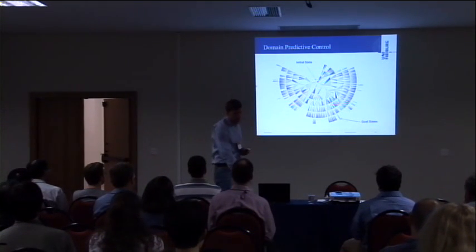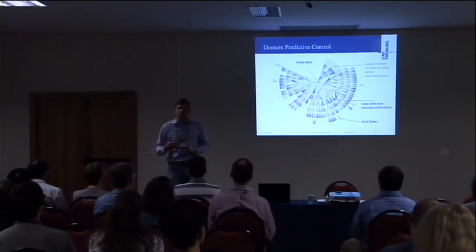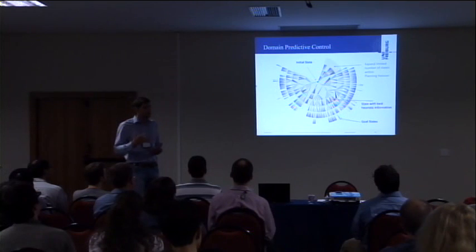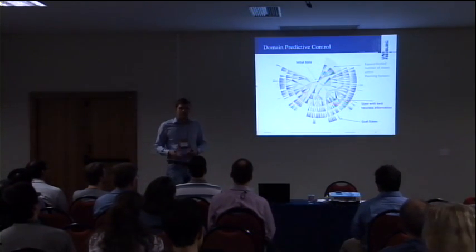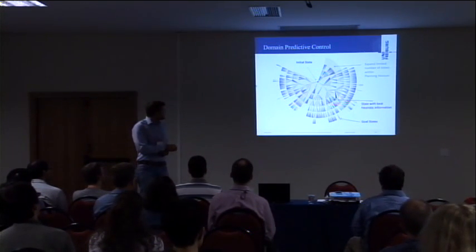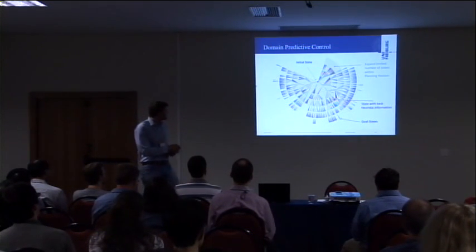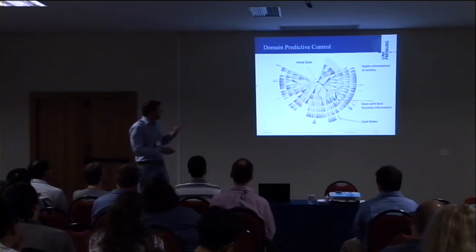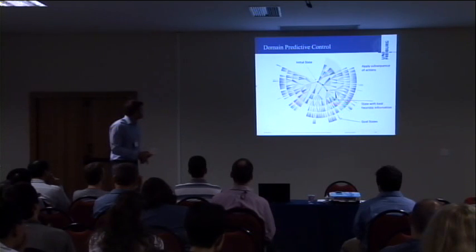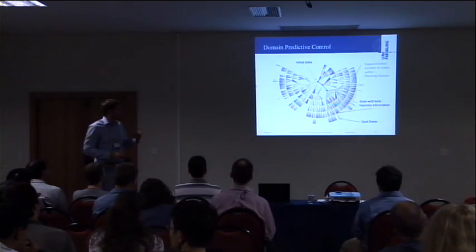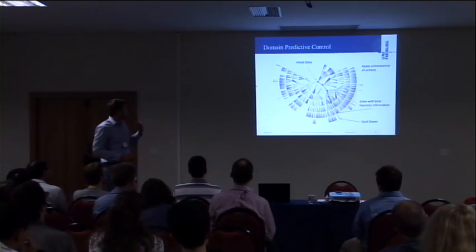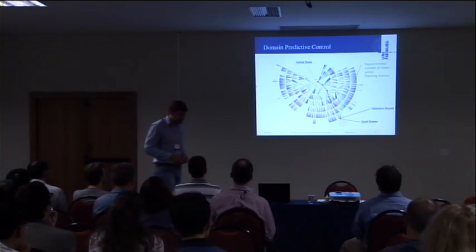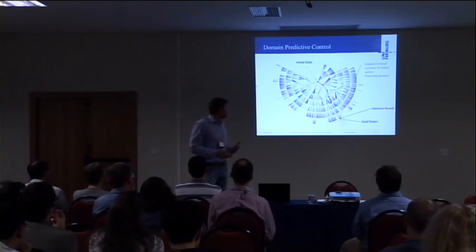That's why we use a prediction horizon. So we only plan to a certain depth of the decision tree, for instance, here 4 steps. And additionally, we limit the number of states to be explored by the planning algorithm. The planner will then return a state which is good regarding heuristic information. And the state does not necessarily have to lie on the path towards the goal states, because in the second step, we just apply a subsequence of actions towards the state which was good regarding the heuristic information of the planning algorithm, and then the horizon is receded, and we start exploring this subtree again. Again, we apply a subsequence of actions towards the state with best heuristic information. Again, the horizon is receded until we have spotted some states which are satisfying our goal conditions. And then we have found a solution.